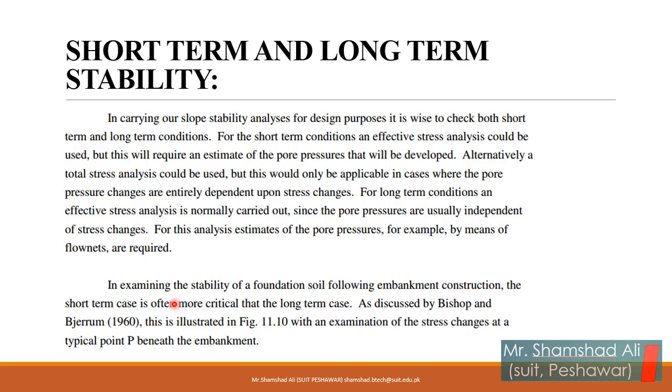Short-term and long-term stability. This is the most important part of today's lecture. In carrying out slope stability analysis for design purposes, it is wise to check both short-term and long-term conditions. When you are going to analyze the stability of a slope, you must check it for the short-term as well as the long-term condition. For the short-term condition, an effective stress analysis could be used, but this will require an estimate of the pore pressure that will be developed. These are the main points.